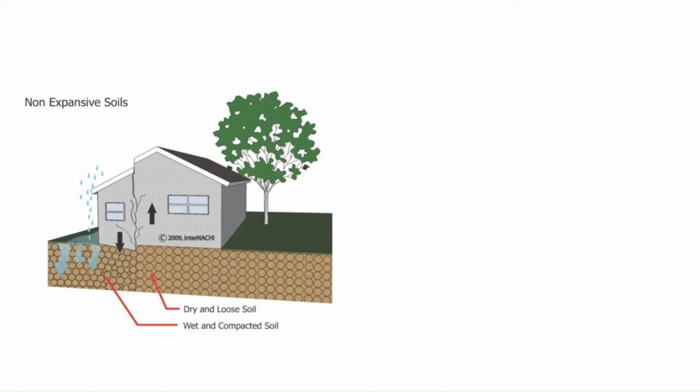This includes 1. Improper preparation of soil for construction. Before exposing the soil to any structural load, it is compulsory construction practice to properly prepare the soil, compact it, and prepare for the estimated expected load. 2. Improper compaction of soil. To prepare the soil for better bearing capacity, additional soil filling and compaction are performed for a better foundation subgrade. Failing to do this results in foundation settlement.